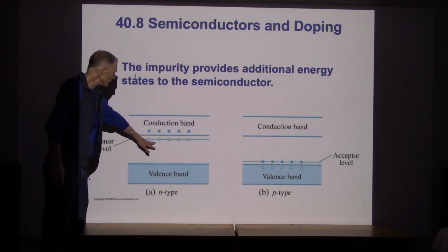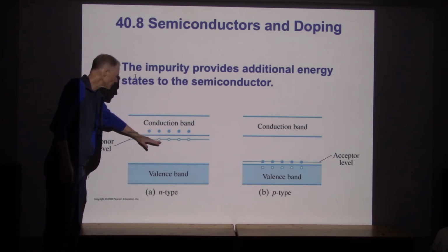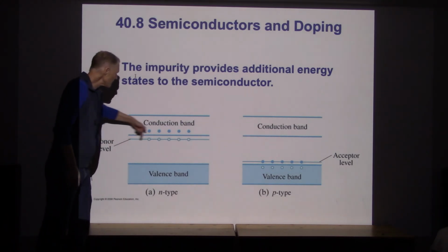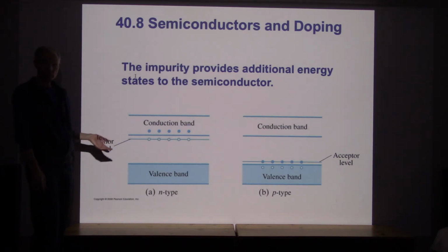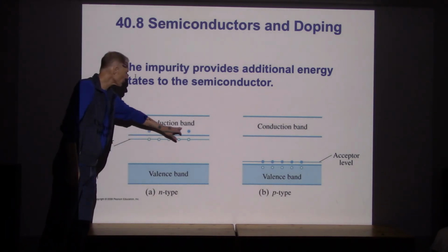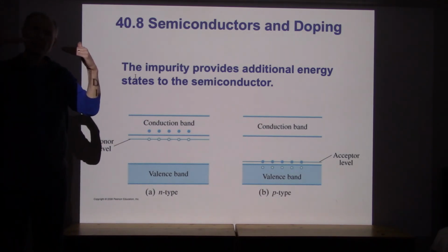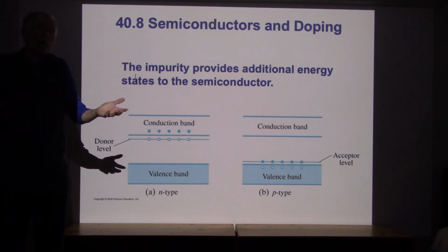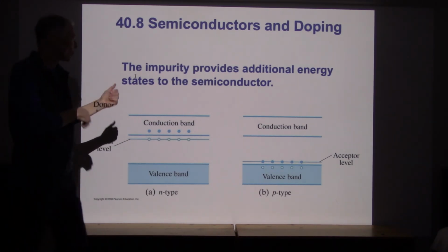And since those new quantum states are within the gap, it's a much shorter jump to move into the conduction band states. So this came in with these donor level quantum states filled with electrons, and for some reason this chart is showing all the electrons are here in the conduction band. Actually, they can just jump back and forth. So they can jump between that donor level and the conduction band back and forth, and that allows movement through the material. So that was doped with arsenic.